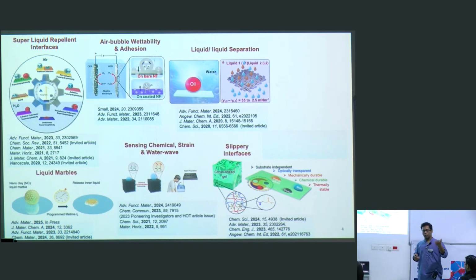So that is possible. We use that coating and put it on an air-water interface. Whatever the water wave produces will give a different height, and based on that, the submerged sensor will experience different pressure and contraction and expansion of the entrapped air. That basically gives the electric signal.